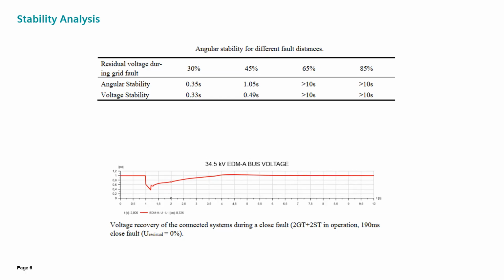Voltage stability defines the fault duration which the complete facility can withstand without having a voltage instability for the whole structure. Voltage instability may occur during motor speed up after slowing down due to a close fault. In that case, the motor tries to draw reactive power in order to speed up, and that reactive power can be supplied only from the generators in island mode. If generators cannot supply the required reactive power, the voltage drops continue, which creates the voltage instability. In industrial plants, for most cases, voltage stability has a shorter duration when compared with angular stability duration.